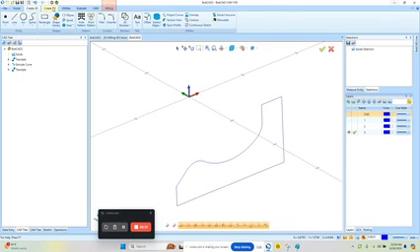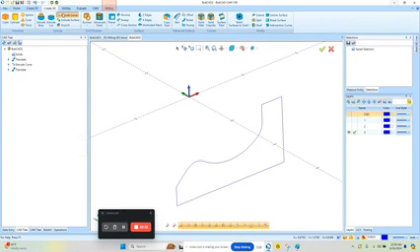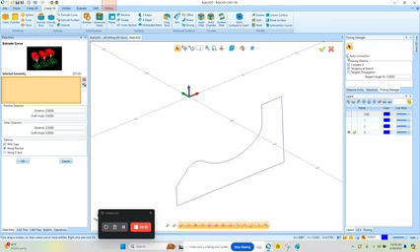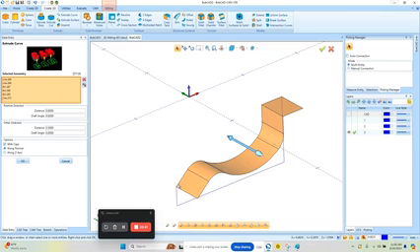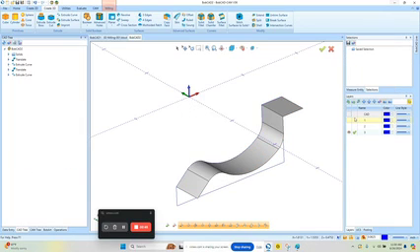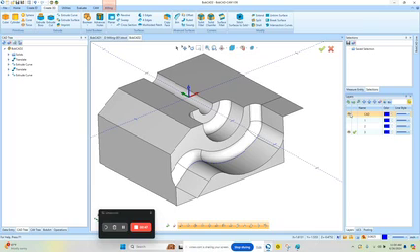From here we're going to do 3D extrude curve. I'm going to turn off auto chaining. I'm going to select through to here and we'll say OK. Alright, so that gives us the surfaces we need to drive a toolpath using parallel with multiple curves.